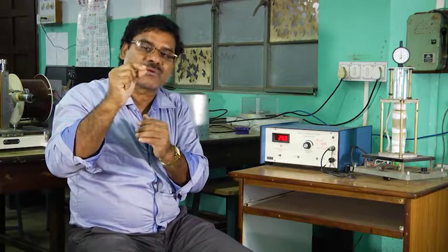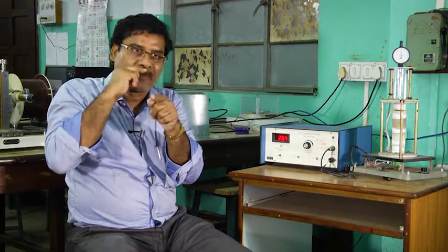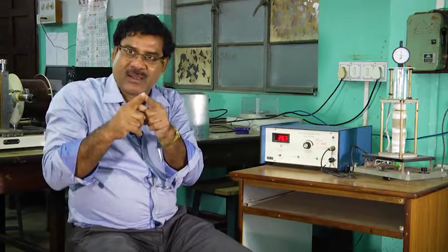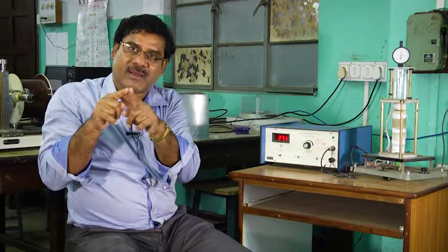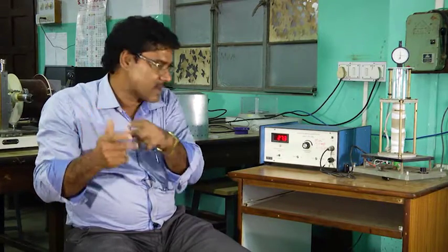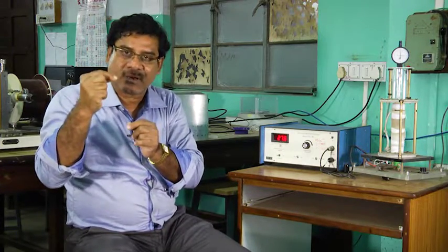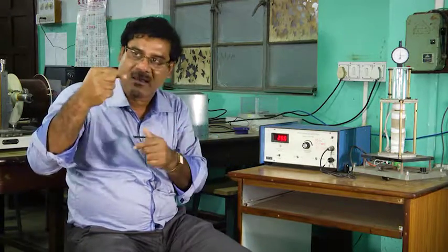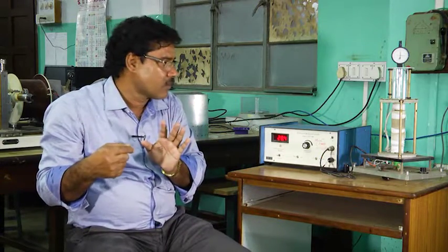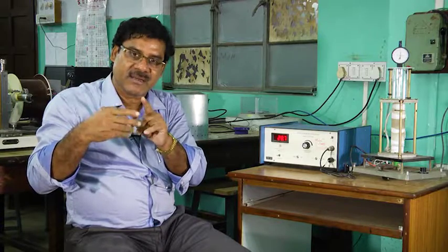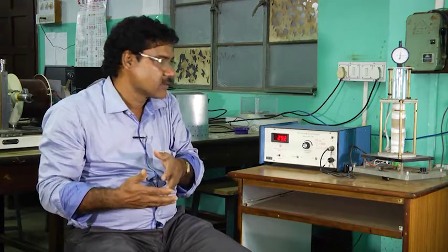Then if it is very close to that 150, plus minus 1. Okay. So, then it is basically the slope, the differential slope. Slope basically at a particular point. So, that is the slope at a particular point. Okay. The slope is nothing but the differential. So, there is a differential circuit also. So, when it is very close to 150, plus minus 1 degree, there it uses this differential circuit for applying current, the power, to the oven. Okay. So, this is the method this power supply, this controller, uses. That is why it is called the PID controller.